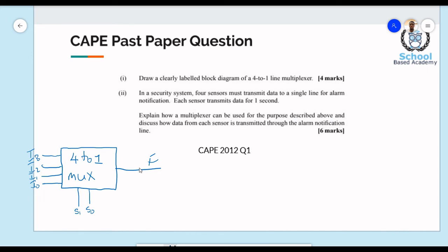So we can use a multiplexer in this way, and I'll just modify the multiplexer that I have here by allowing our multiplexer to be connected to a clock. This clock is a 2-bit clock, which means that our clock always goes 00, 01, 10, 11, over and over and over. So this 2-bit clock feeds information along the lines S0 and S1.